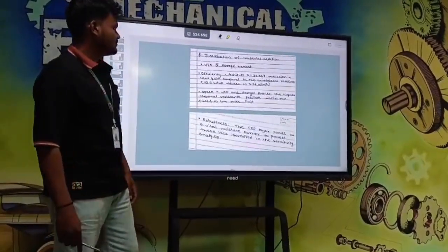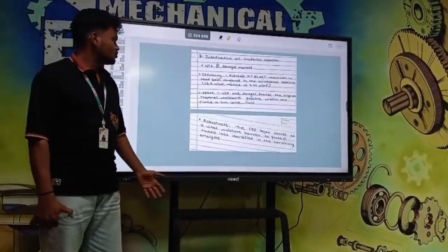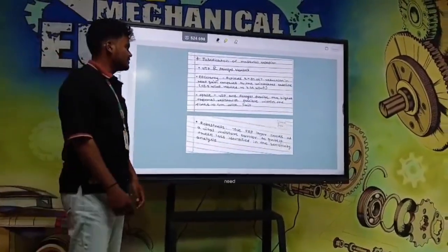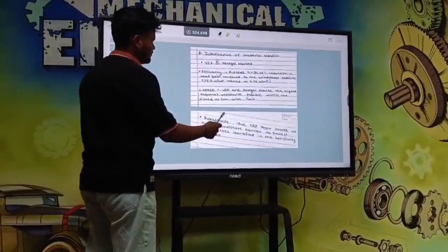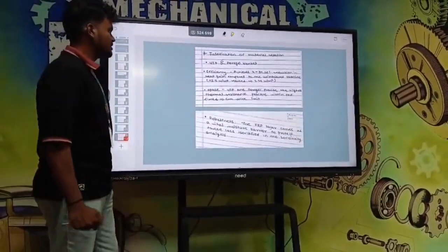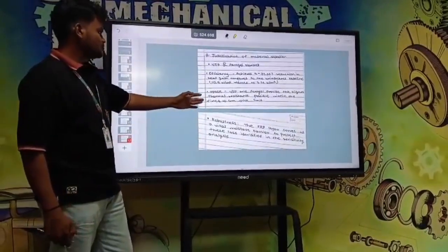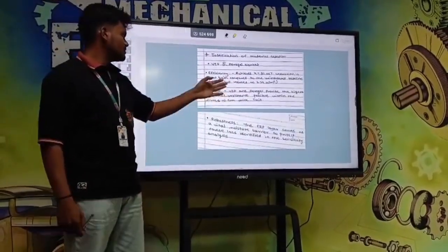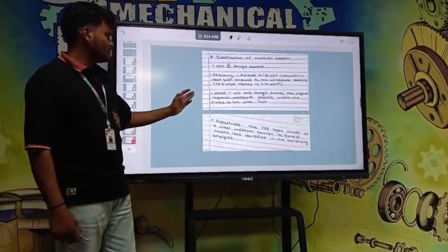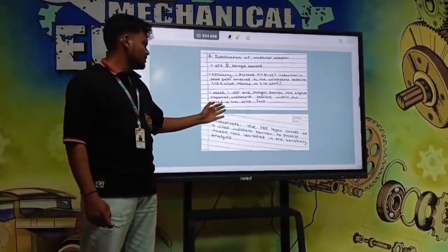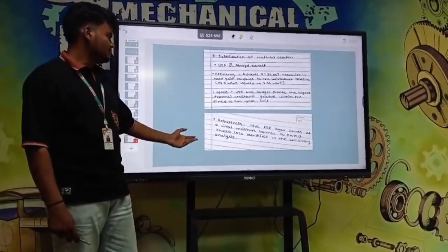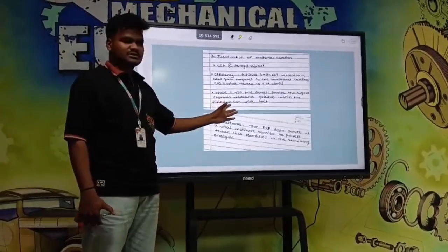Last is the justification of material selection: why I selected VIP and the aerogel blanket. For efficiency, the thermal resistance is higher for these materials, achieving a 97.0% reduction in heat current compared to the uninsulated baseline. For space, VIP and aerogel provide the highest thermal resistance possible within the fixed 10 centimeter thickness that is given.